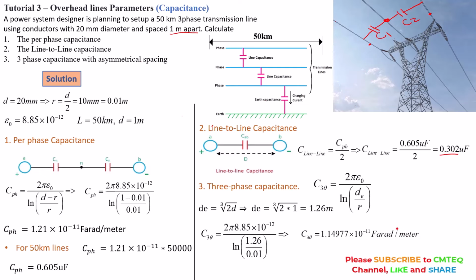As always, we need to multiply this by 50,000 meters, so that we can get the capacitance of this 50 kilometer line. That gives us an overall capacitance of 0.575 microfarad. As you can see, the three-phase capacitance is very close to the per phase capacitance calculated between the phase and the neutral.